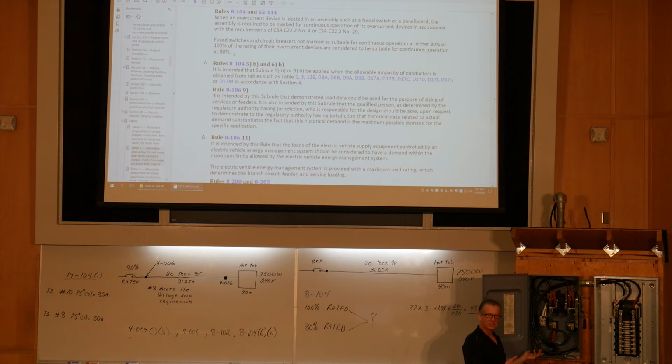It has the ability to dissipate the heat. On the panel board, the enclosure would be wired, with more space and more venting. You cannot put a 100% rated circuit breaker in an enclosure that's not marked as suitable for 100% rated equipment. They work together, breaker and enclosure.